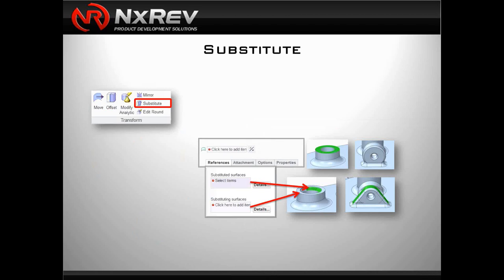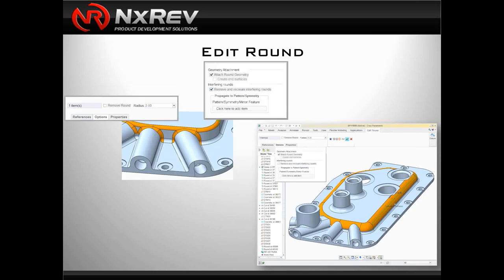Substitution is going to, again, allow us to substitute an existing surface for a new surface. We did the example with the little triangle tab and the rounded, converting it to that rounded surface. Probably one of my favorite features has to be Edit Round. Again, we simply selected a round, either deleted it or changed the value.